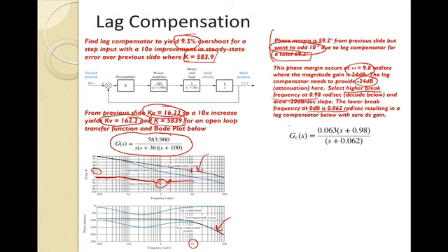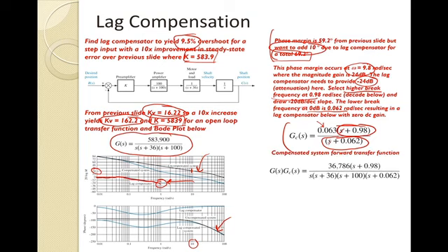That way we design our lag compensator with 0 DC gain. So that resulting lag compensator, based on that above text, has our 0 here, our higher break frequency, and then our lower break frequency here, and then this gain here designed so that at s equals 0, this all multiplied divided by this will give me a gain of 1. Okay, so that's our design for our lag compensator.